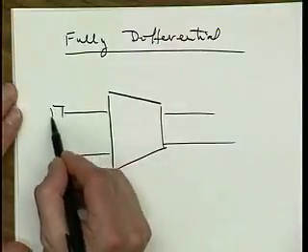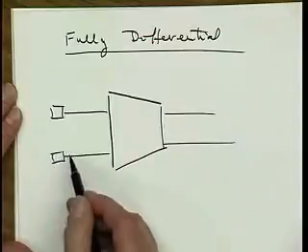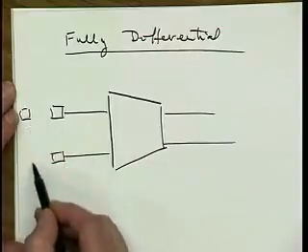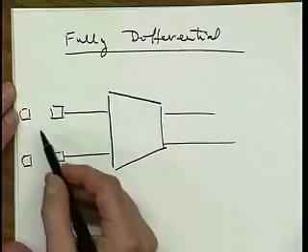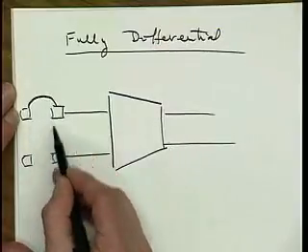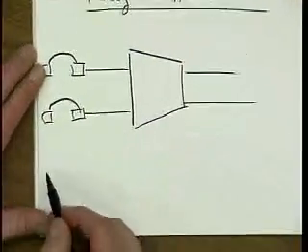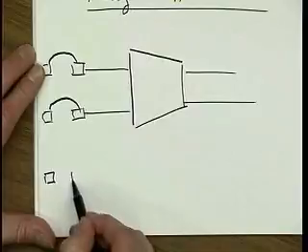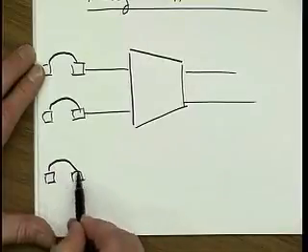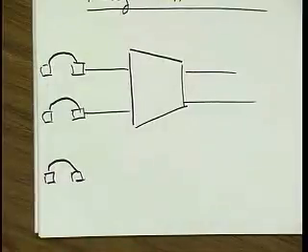One common case is, suppose this was the input of our A to D converter, and it comes into the chip through bond wires. Well, somewhere else on the chip there is also a power supply, and perhaps it's a digital power supply. And we know that inverters are really horrible things, right? They sit there, and then they short circuit the power supply, and then they sit around again.